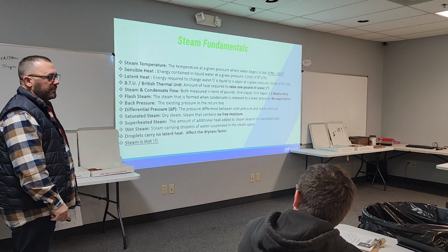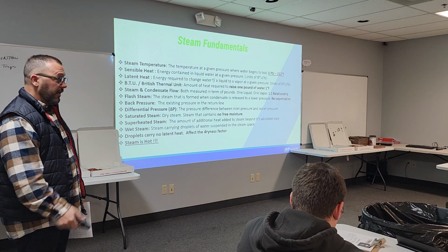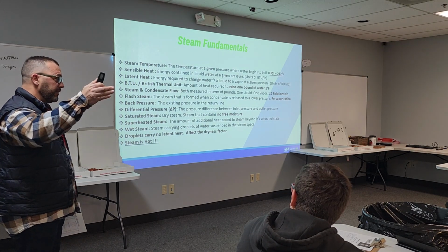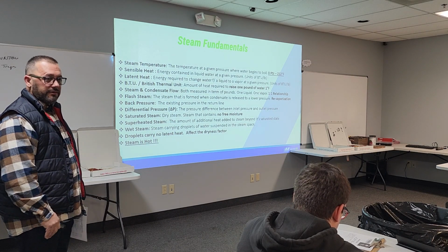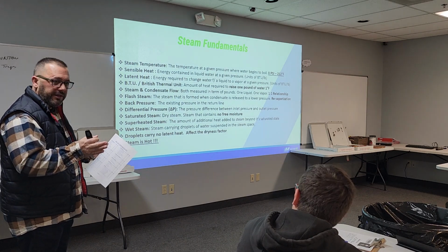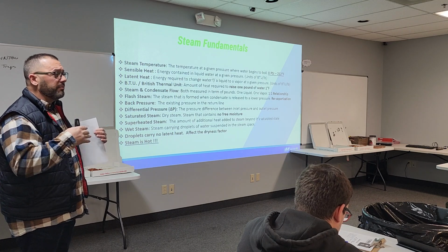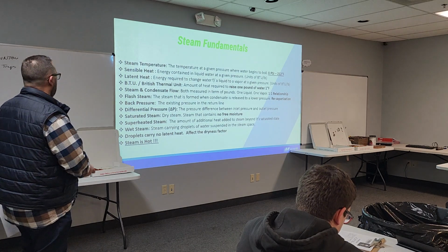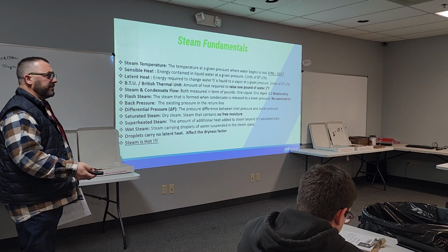In the case of Ohio State, roughly 42 miles of underground steam piping, and if you want to get steam in a district heat fashion to West Campus, and you want it to be steam when it gets there, then you're going to superheat it. Then we'll use de-superheaters, which basically look like a spool piece in line with some atomizing nozzles, which all they really do is inject condensate right back into that superheat and bring it back down to the saturated steam level. Wet steam is steam carrying droplets of water suspended in steam space.